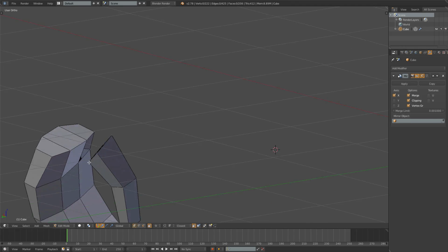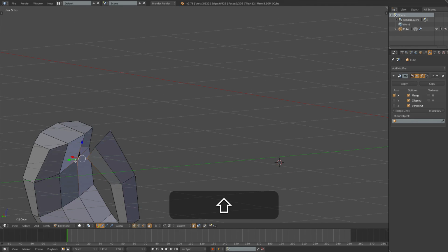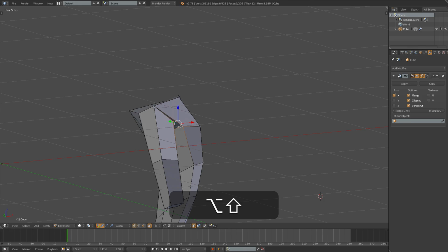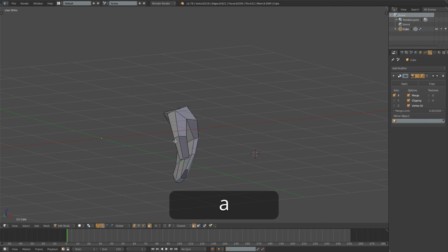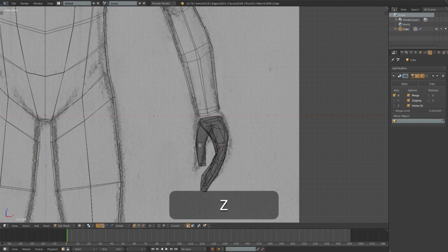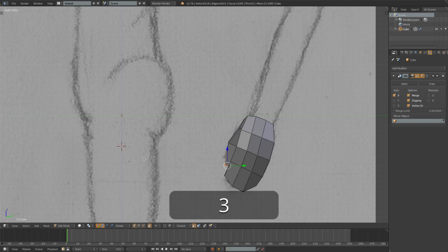And then in vertex mode, I'll select this vertex and that vertex and Alt-M to bring up the merge menu and just merge at their centers. And I'll repeat that for each of these. Alright, so this last one here, Alt-M, merge at center. Alright, so now it is attached, and you can just go around and do some last adjustments.